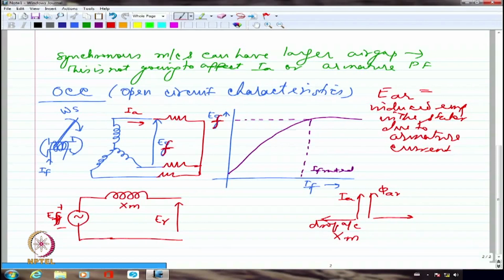If there is leakage, I have to show one more reactance which will represent probably the leakage which will not link with both stator and rotor. There will be definitely total flux produced if I say is 1 Weber. Maybe 0.9 Weber will link with both the stator and rotor. Rest of 0.1 probably will link only with individual member alone.